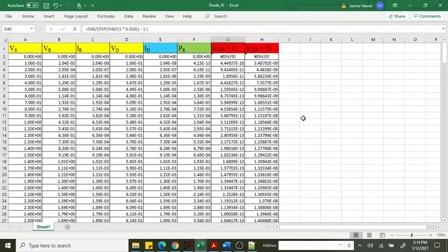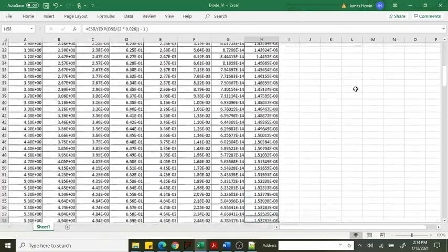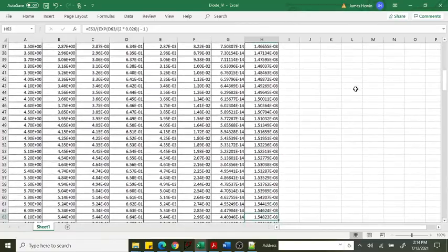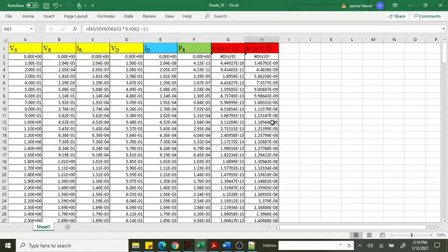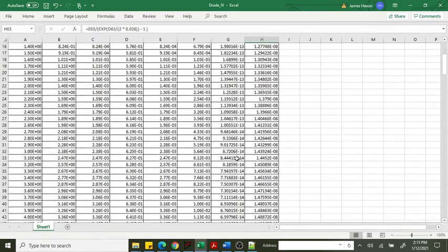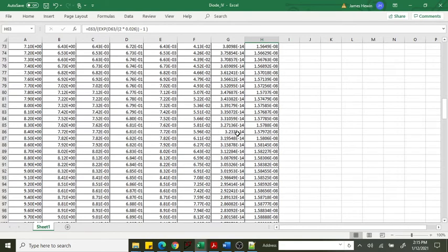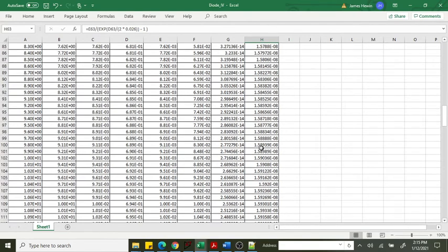Whereas for a practical diode, where N is closer to 2, you're looking at around nanoamps. So it's still a very, very small current, nanoamps as opposed to milliamps, which we would have under forward bias. It's very small, but still different from N equals 1.